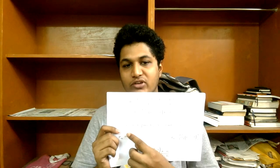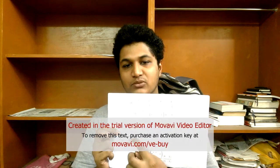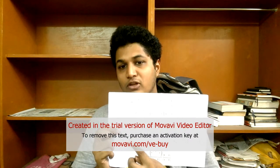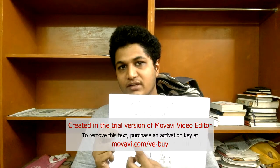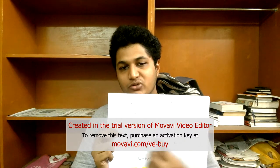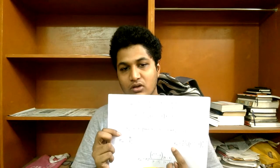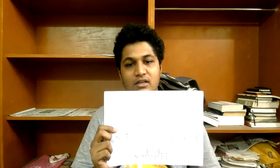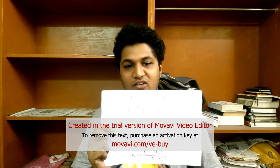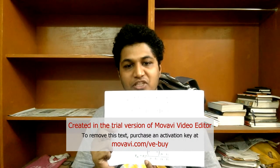The next step is to calculate the actual swept volume, which gives you your mean effective pressure as work done divided by volume swept. Because you have to calculate your swept volume to get the exact answer for your mean effective pressure, you include your swept volume in terms of V1, V2, V3, and V4, which is how you get this equation over here. To sum up, it's just math; I'm just trying to walk you through how you actually calculate it. You get your final equation as the mean effective pressure in terms of compression ratios, pressure ratios, and the initial pressure.